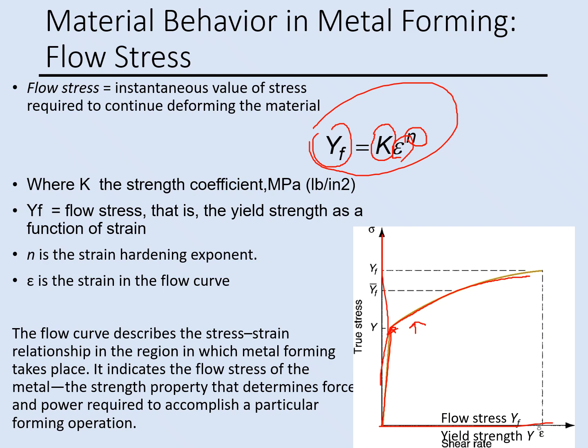As we talked about dislocations before in alloys, when you apply load, you have plastic deformation. This defect, dislocation, is a defect. Dislocations will tangle with each other, and it makes plastic deformation harder and stronger.